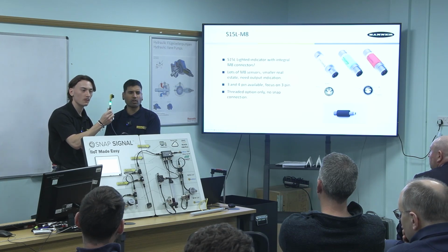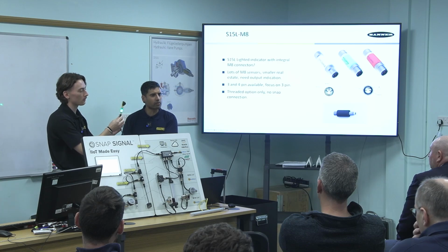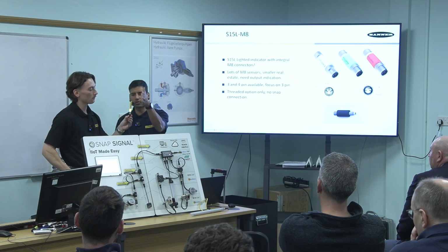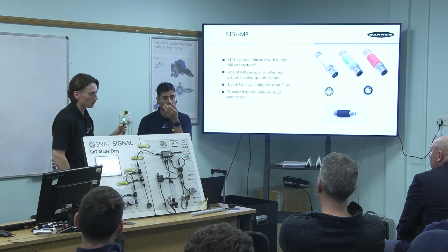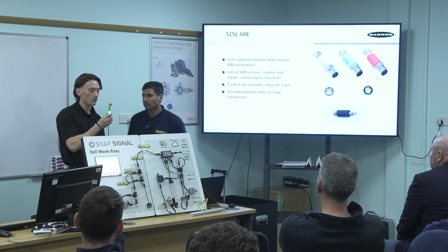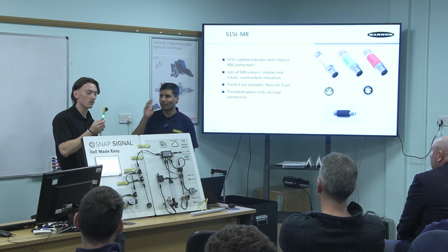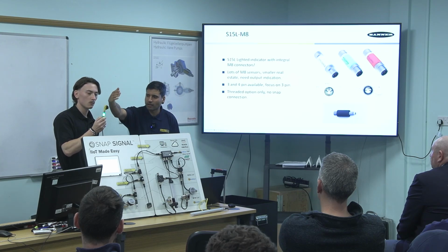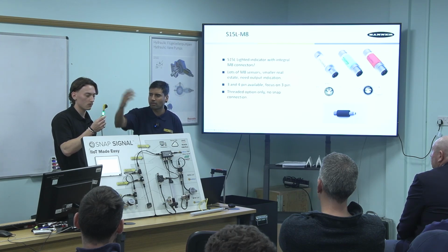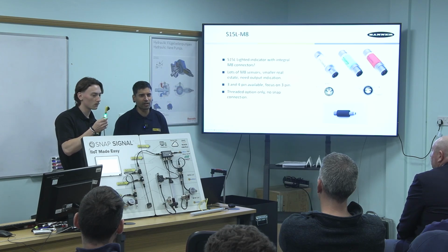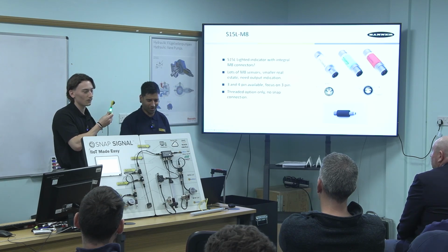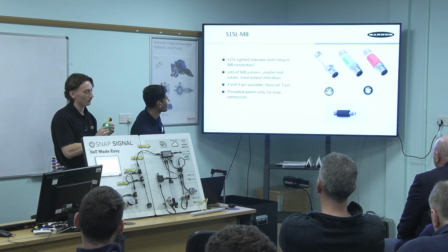It's quite good if you've got sensors and you can't access them, but these are quite good for fault identification on the sensor. So you can see sometimes, if you've got a bunged up sensor, if it's not an IO-Link or so, you can actually pop one of these inline indicators onto the sensor so you can see the status. So it's all part of our visual factory really, brightening up your process.